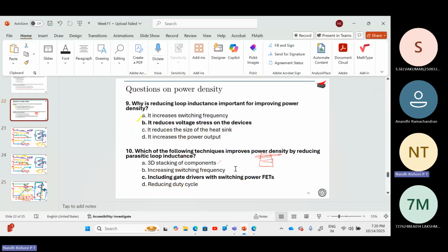Now, instead of physically having a separate gate resistor and gate driver, people have started integrating them within the device. You will get a power device in which the gate driver is already there, so you just need to give the microcontroller pulses. The gate driver IC has been realized monolithically within the power package itself, similar to how you manufacture ICs.